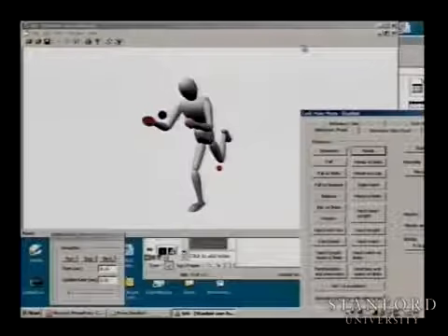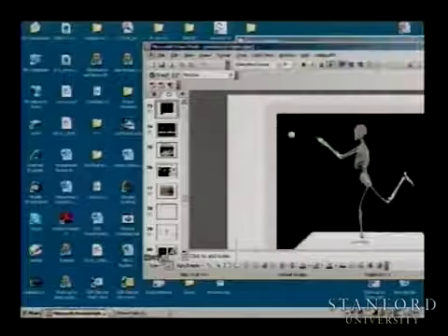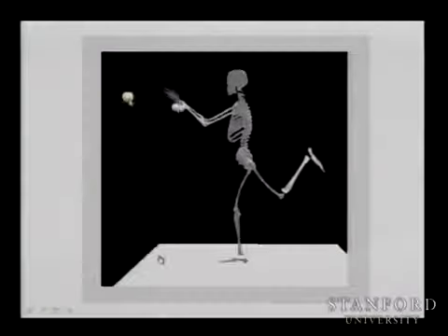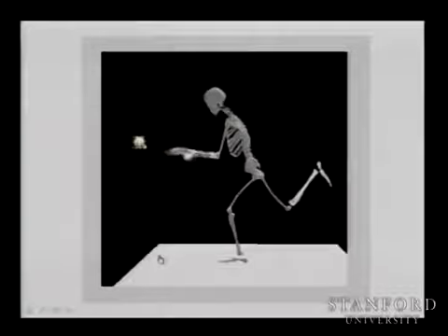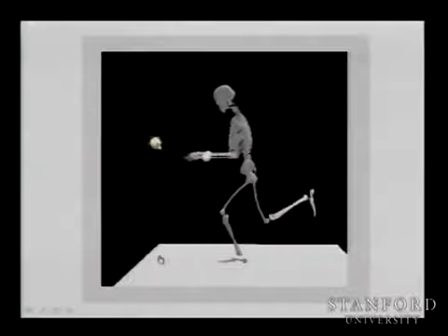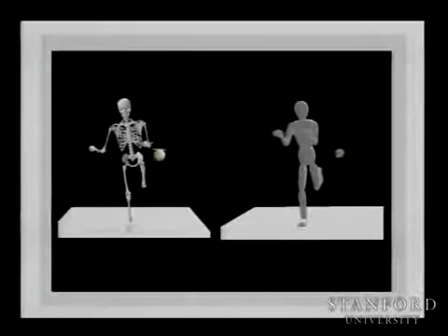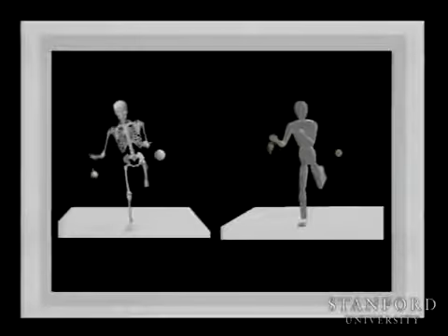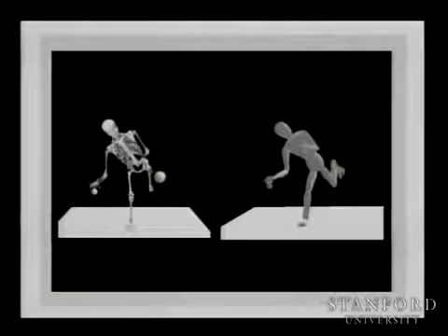All right, so now let's go back to this. So this is what we're doing. We are controlling one point and the body is adjusting through a criteria in the null space, and now you can move it to the robot, not as a trajectory you're copying, but as a criteria that you're applying to the robot.